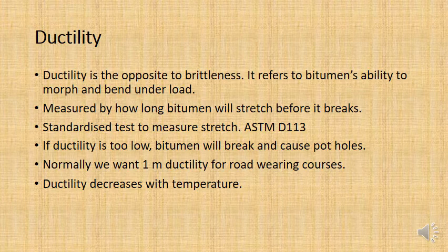So how do we measure this? We take bitumen and we stretch it, and we see how long it can be stretched before it snaps. Now there's a very standardized test for this called the D113, or the ductility test. You will be doing this when you do your transportation modules. Again, unfortunately I can't do this with you in building materials because we don't have a lab, but you will be doing this in due time with Dr. Abbas.